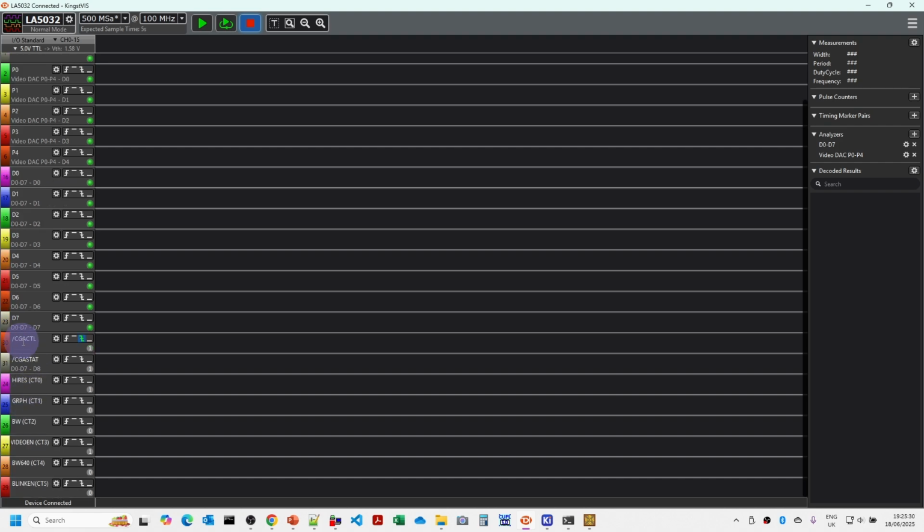We've also got the CGA control chip select line, the CGA status chip select line, and I've also hooked up these outputs on the pins on the complex PLD for the various status register values. So things like the high res mode, black and white flag, and the blink enable, for example, we should be able to see those values directly.